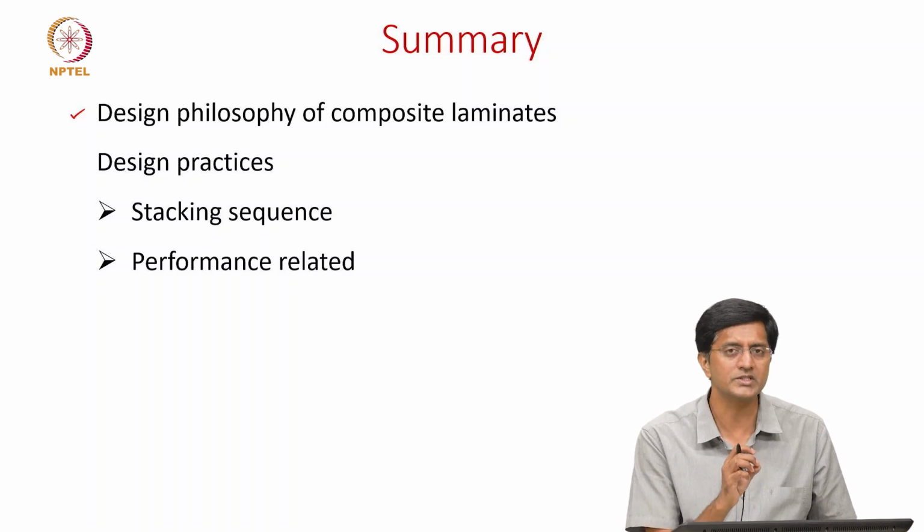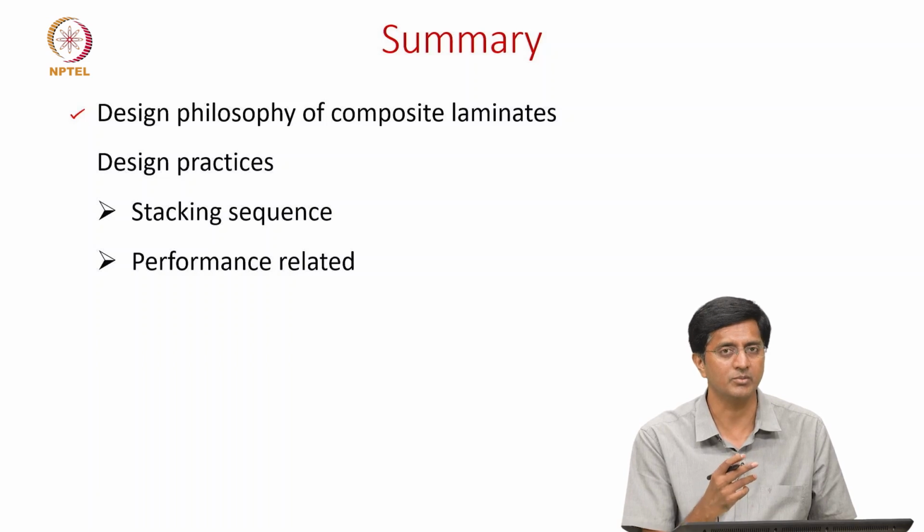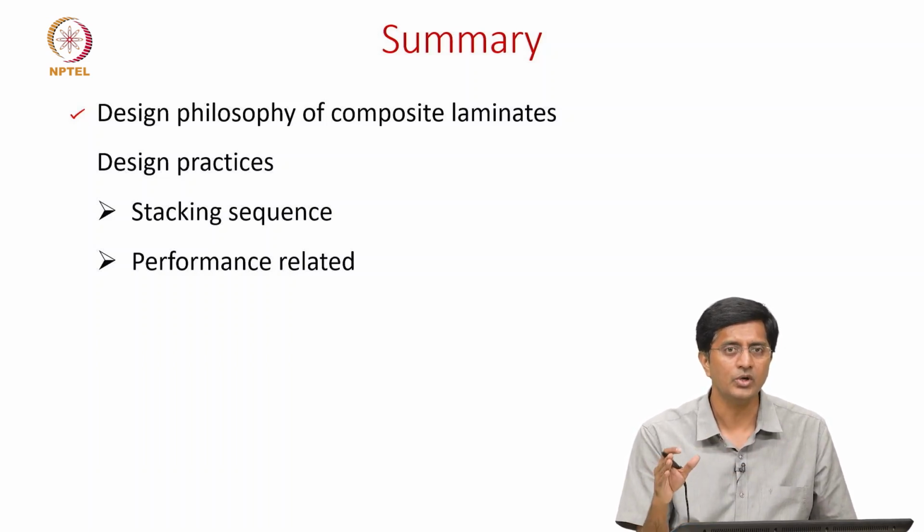And when we discussed fatigue failures, we emphasized that in metals it takes a long time to initiate a crack, but once it is initiated and reaches a critical value, the time to propagate is less. For composites it's the other way: the damages can start in the early cycles itself, maybe around 1000 cycles, but for the crack to grow it takes a long time, because the fibers in the composite act as natural hindrances for crack growth.